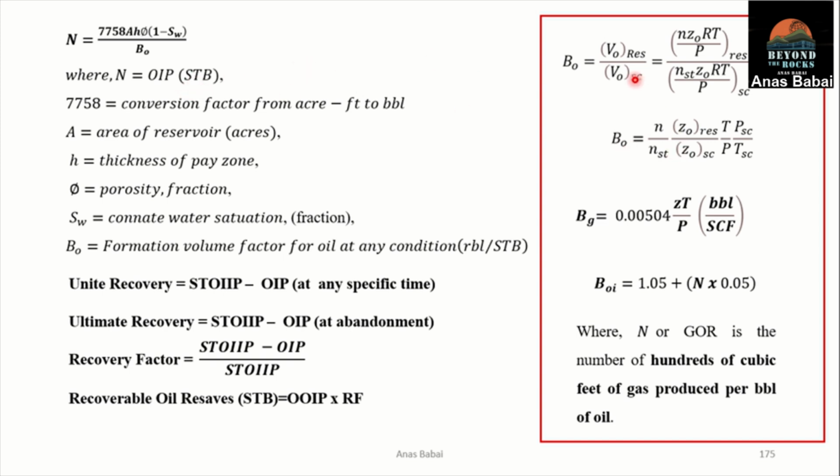So the basic assumption for calculation of the formation volume factor is using the ideal gas equation, which is nZRT divided by P, and this is the volume, and we know that the equation is